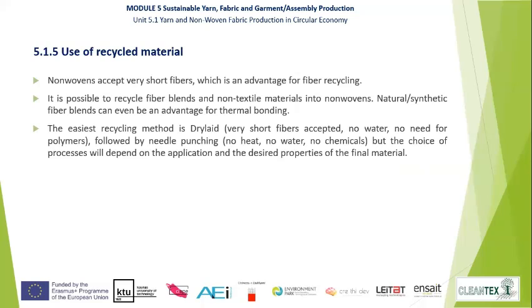How to use recycled material into a nonwoven? The advantage of nonwovens is they accept very short fibers, which is an advantage for fiber recycling. And it's possible to recycle fiber blends and non-textile materials into nonwovens. Natural synthetic fiber blends can be an advantage for thermal bonding, for example, because synthetic fibers will bond the web.